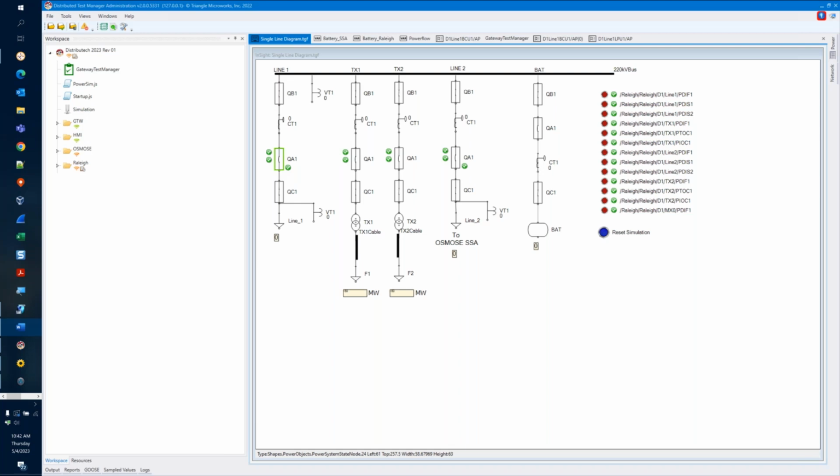As you have seen, if we follow the design principles and best practices being discussed today, it's going to result in an SCD, which essentially contains the 61850 substation's equivalent to a traditional single line diagram in the form of the substation section, a communications drawing in the form of the communications section of the SCD, your SCADA data maps in the form of MMS reports and the associated data sets, and kind of the equivalent of your interconnect wiring, and that's going to be in the form of your GOOSE and sampled value configurations.